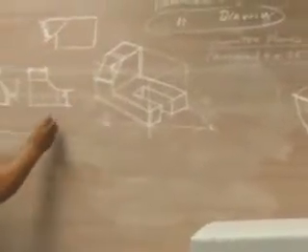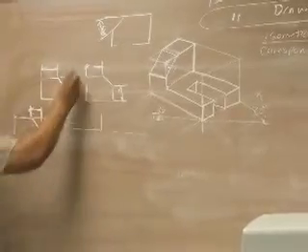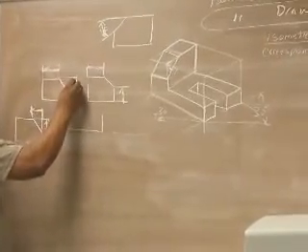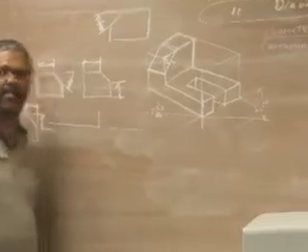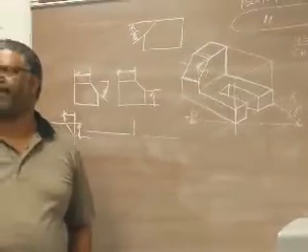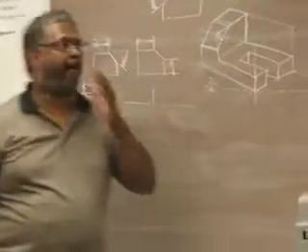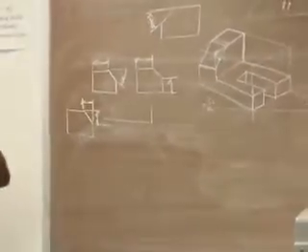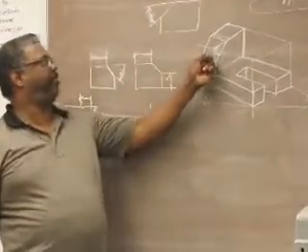But when I transfer that to an isometric, I can only do this way or this way, because the angle looking at it orthographically is not going to be the same isometrically. So from the front view, that angled surface would look flat. Yeah, from the front, this will look flat.